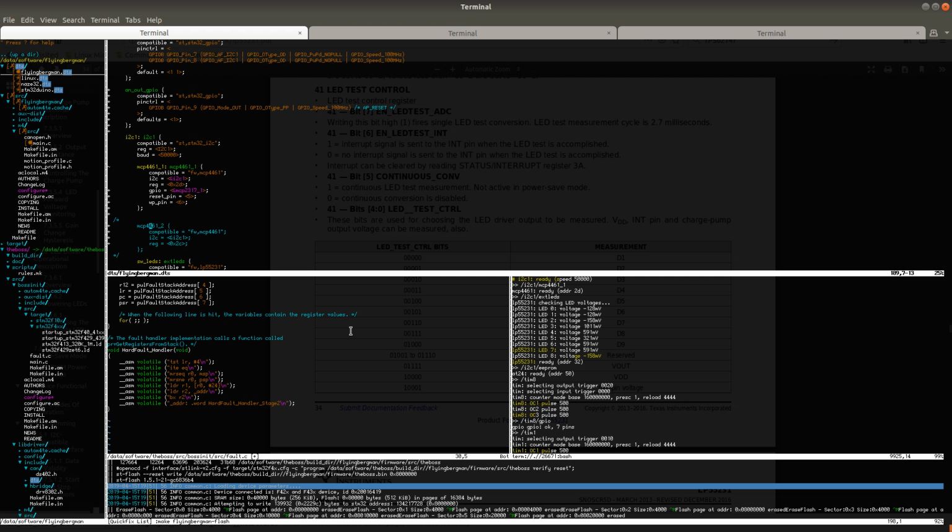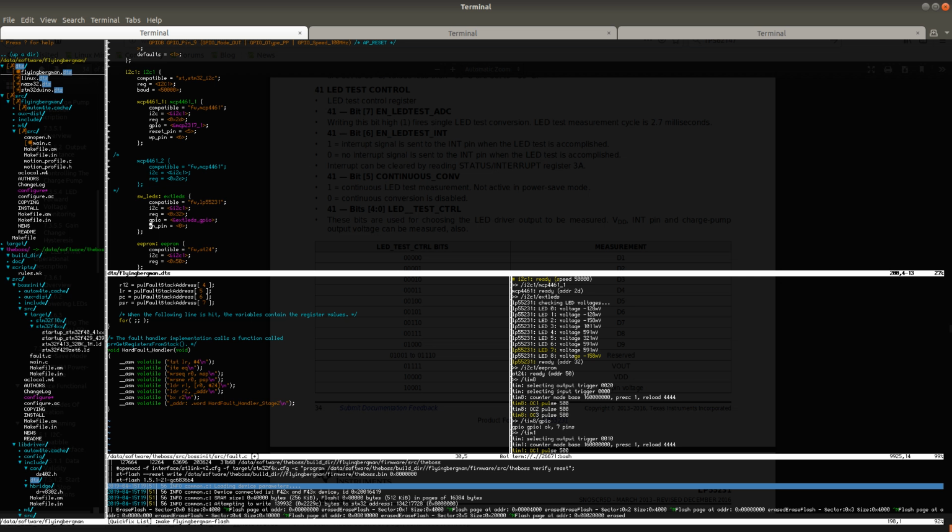Okay, so the most obvious way to implement this is to export an interface from the LED driver, and this can be something as simple as just a memory interface, which would allow me to just read the state of the LEDs. However, that kind of breaks the whole abstraction thing. It suddenly requires that the application knows about exactly which driver the LEDs are using. So I'm trying to think about some better way to do this, so that I don't have to rewrite the code later.